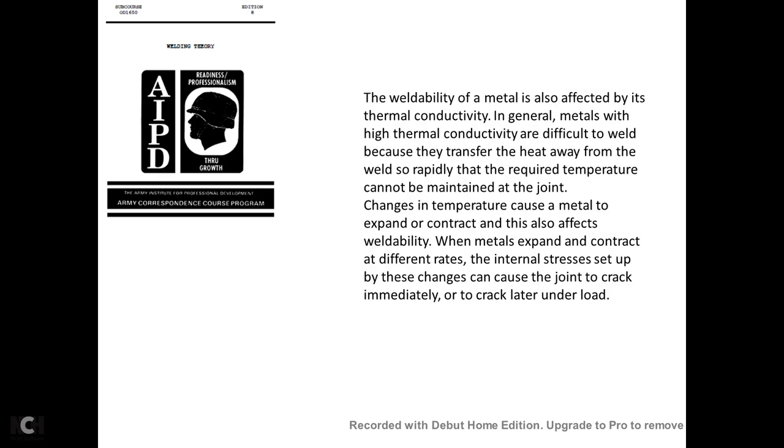The weldability of a metal is also affected by its thermal conductivity. In general, metals with high thermal conductivity are difficult to weld because they transfer heat away from the weld so rapidly that the required temperature cannot be maintained at the joint. Changes in temperature cause metal to expand and contract. These also affect weldability.